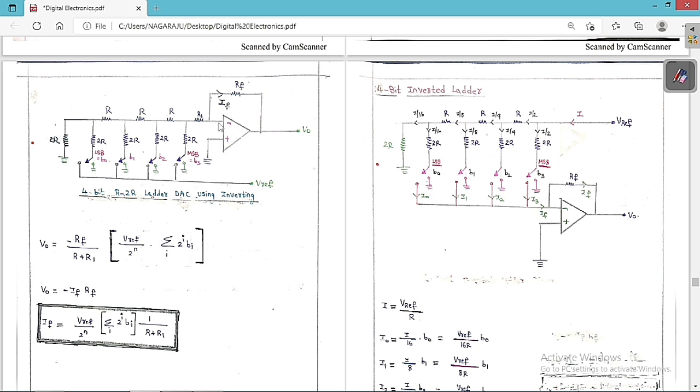Suppose I wanted to tell you, the input currents are always equal to 0. So this is also 0 volt. Whatever current If passes through R1 should pass here also, because the current into the input is 0. So here it is If.